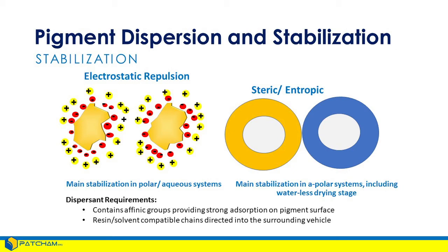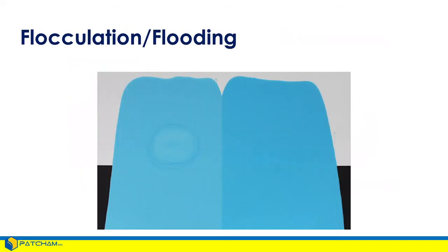So think about how we in the paint industry test this. Well, that's why we do drawdowns and rub-ups. We apply the paint, we allow it to dry, and while the paint is still fluid, if we move it around, it is not fluid enough to recover. So the case of color change indicates that, when we do the rub-up, we've applied shear, we've put energy into the system, and if it changes colors, the pigment that was flocculated will be deflocculated by the shear that we put in. And if the paint is still liquid enough to move around, those pigment particles will reflocculate.